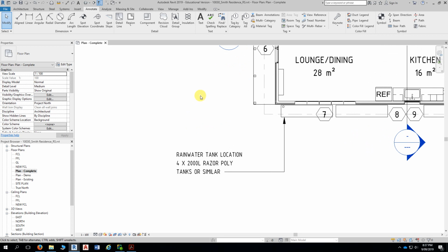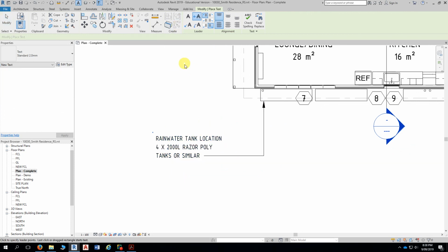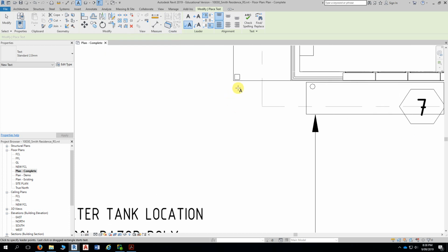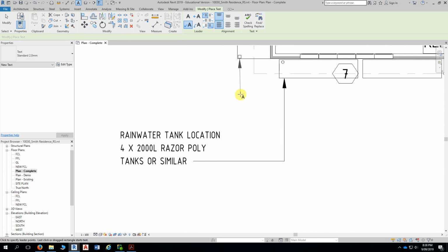So again, if you're placing another note, which obviously you are, above this one, select the note here and do a create similar, this one up here, create similar. In this case it's going to be a 2-segment leader, this one here. And you're going to describe the post, so you need to get in nice and close and then start the first segment of the arrow from here, moving down, so keeping it vertical.